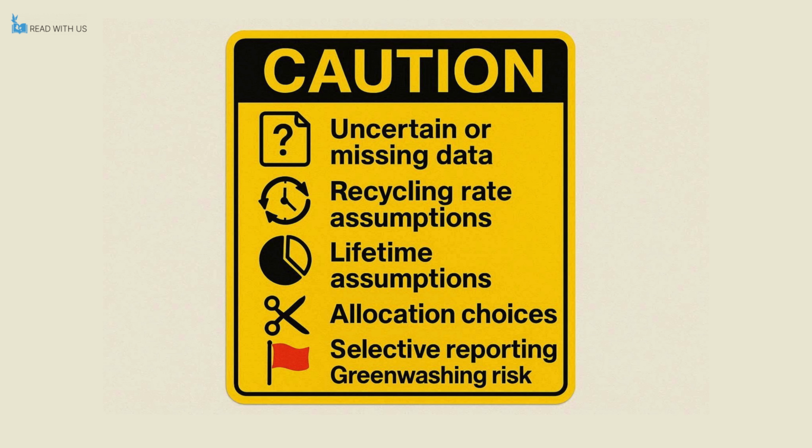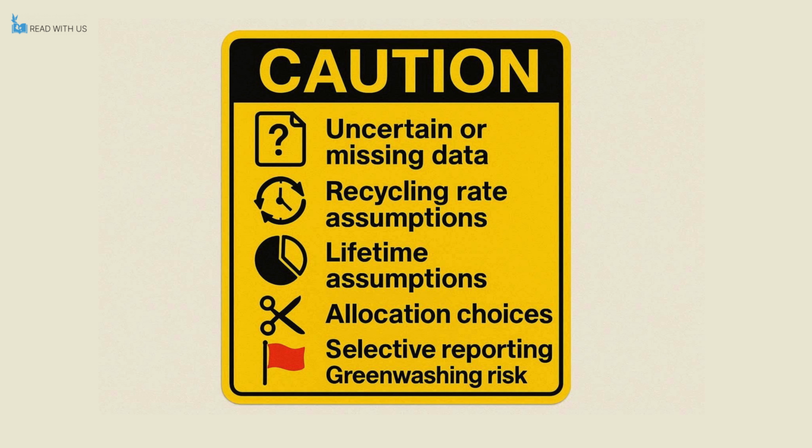Limitations of LCA include uncertain or missing data, assumptions about recycling rates and lifetimes, allocation choices for byproducts, boundary cutoffs, and the risk of selective reporting that leads to greenwashing.